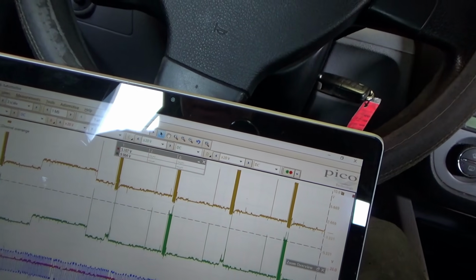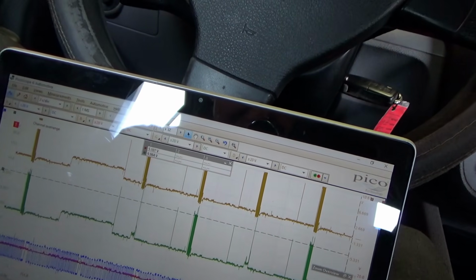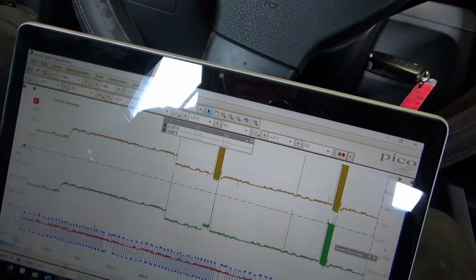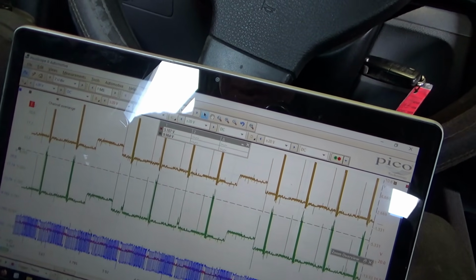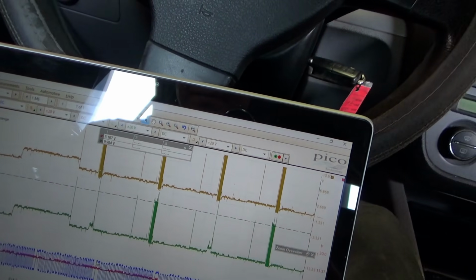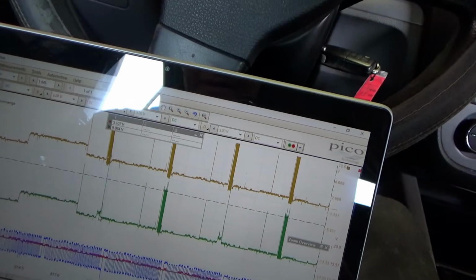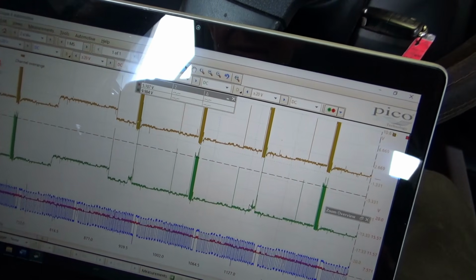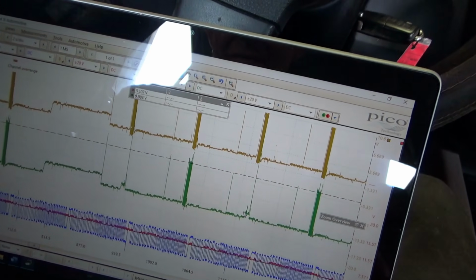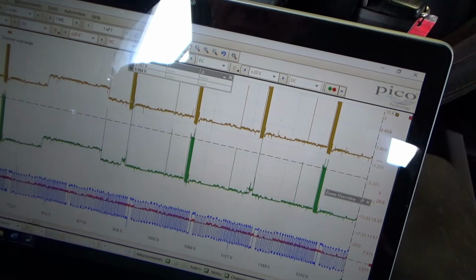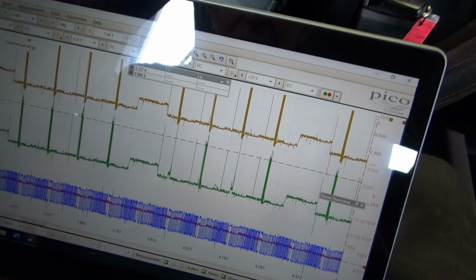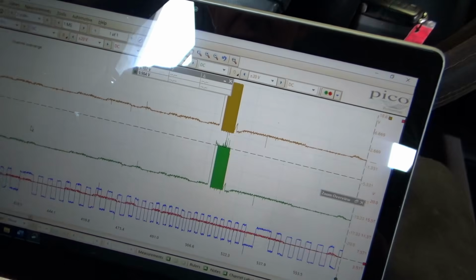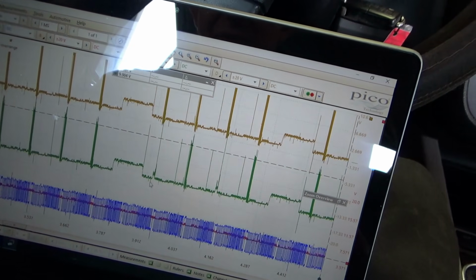Does that make any sense? And we know that there's 2 sync notches per crank revolution. So it fired, let's say at 0 degrees, this is 360. That would make sense. I don't know what the synchronization here is, but here it didn't fire the injectors at all. This is just based on the crank sensor.